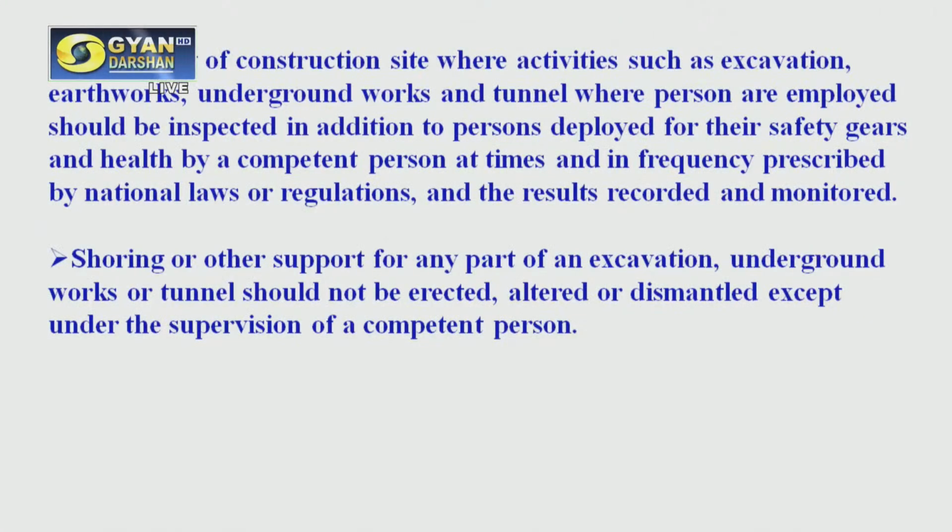Next is that every part of the construction site where activities such as the excavation, earthwork, underground works or tunnel where persons are employed should be inspected, in addition to the persons deployed, for their safety, gears and health by a competent person at times and in frequency prescribed by the national laws or regulations, and the results recorded and monitored. That these places should not only be inspected, whatever we have found there should be recorded and these records should be maintained for further reference basically. The shoring or other support for any part of excavation.